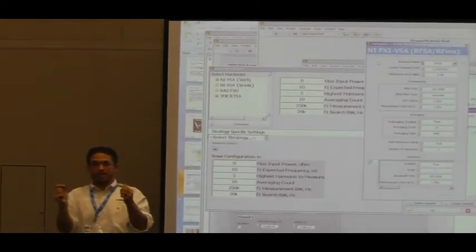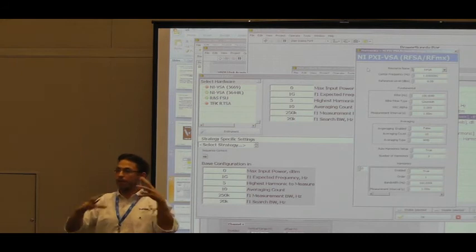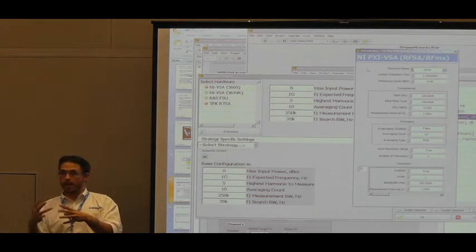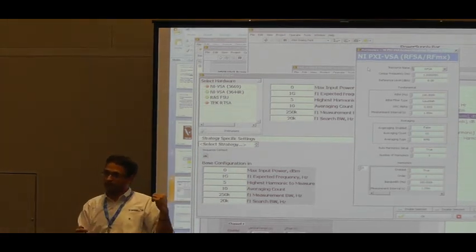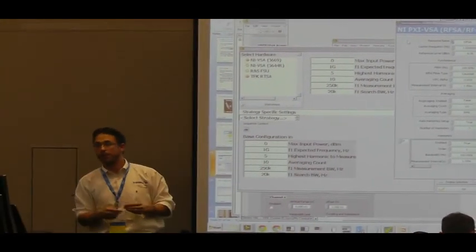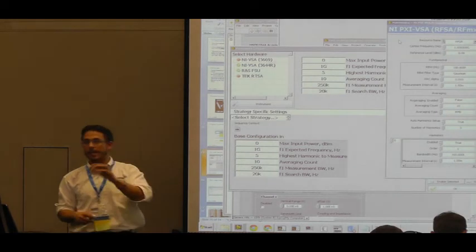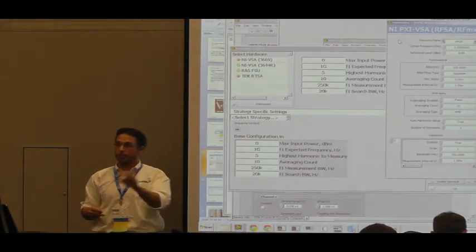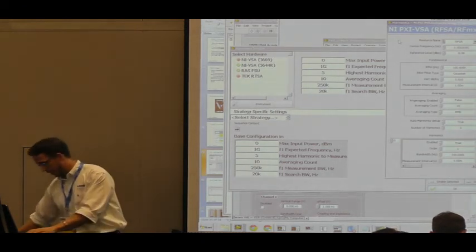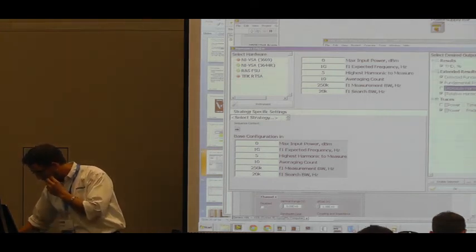And I know how to talk, and it's not going to be, you set this setting that goes straight to the user, or you set this setting that goes straight to the hardware. They coordinate between each other. It is a lot more complicated than just a straight switch statement in your code. It's the way a lot of people, that Bravo Foxtrot enum that we saw up front, that's all that was. That was their HAL. They just had a big old enum up front that said, which one am I doing? Go ahead and do different things. But in order to prevent this leakage through, you truly do need to have a little bit more intelligence cooked into the system itself. So that's the idea of an expert. Something else to think about. So we'll go ahead and hold up on the strategy for a second.